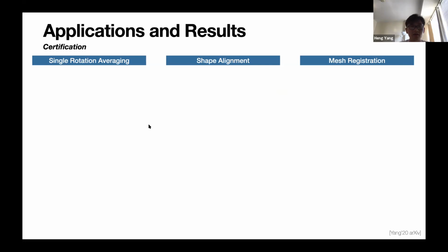And then the other line of designing certifiable perception, as I showed, is doing certification. So certification is different from relaxation. Basically, in certification, you actually have two steps. In the first step, you solve the TLS problem directly using RANSAC or GNC, these heuristics that do not offer you guarantees. And then you add another layer of these heuristics to try to give them certificates.